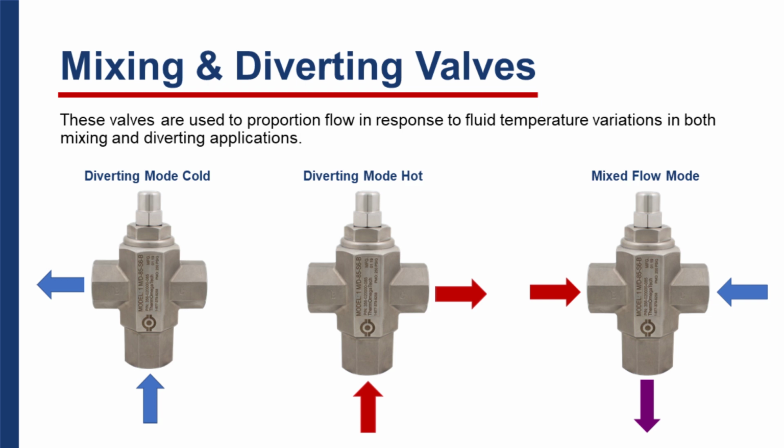That same valve, believe it or not, can also be run backwards. In other words, you can have the hot coming in from the left side port, the cold media coming in from the right side port, and a mixed tempered outlet to whatever temperature you desire.